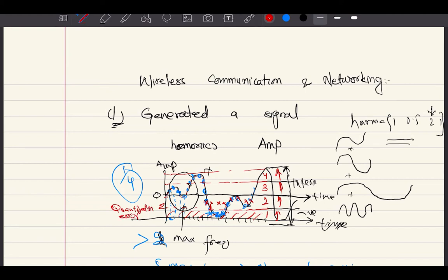Your quantization error can be reduced by increasing the number of levels, but if you increase the number of levels, you have to pay for it in the form of overheads. You don't want too many levels, because some levels will not contain any data points, and those quantile intervals will go to waste.